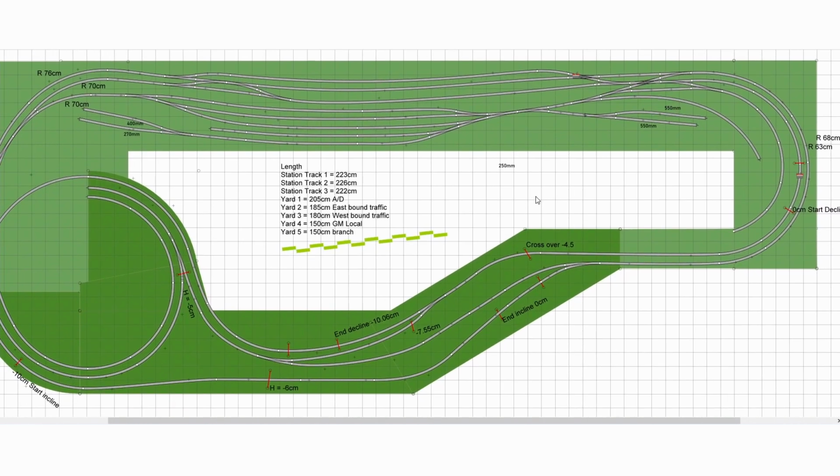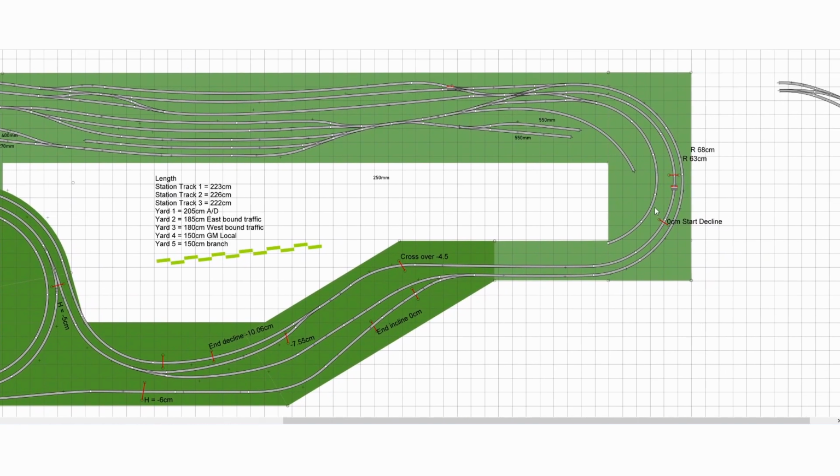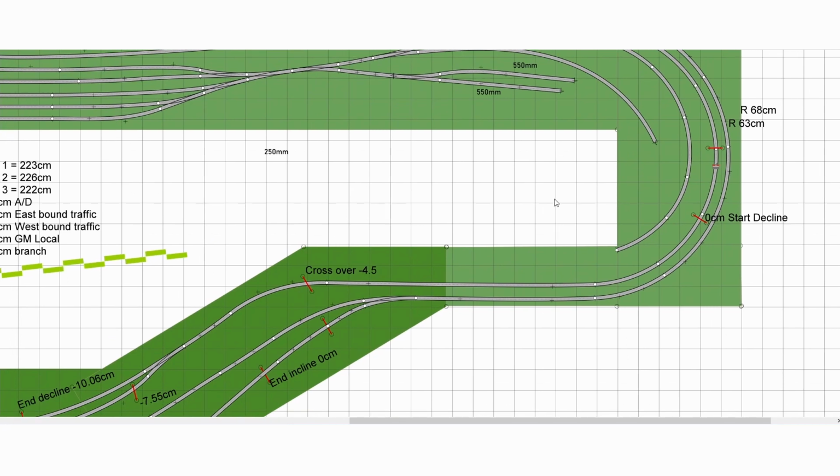So now let's have a look at the gradients and where they start and stop. You'll see 2 red lines. This red line here, the first one, is where a gradient starts. In this case, it goes from 0, that's the height of the top deck, to -4, this line right here. And there's also a gradient onset. So the gradient actually starts here around 35 centimeters earlier, and this is to gradually get into that gradient. But for calculation measures and to be on the safe side, I actually start calculating from this line here.